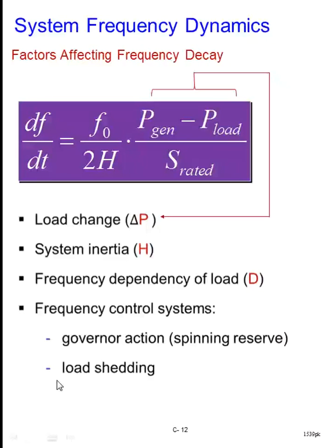Because when we have a load increase, if the system operator feels that you don't have capacity for more power generation against the increased demand, then they will apply some kind of action depending upon the change in the frequency deviation against the increased load demand.